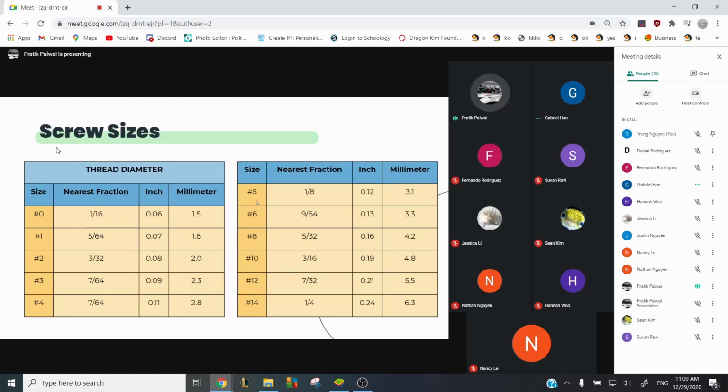For example, a commonly used screw size is a quarter-20 screw. This means that the thread has a quarter-inch diameter and there are 20 threads per inch. So if somebody asked you for a quarter-20, 2-inch screw, that means the screw is a quarter inch wide, has 20 threads per inch, and is 2 inches long.